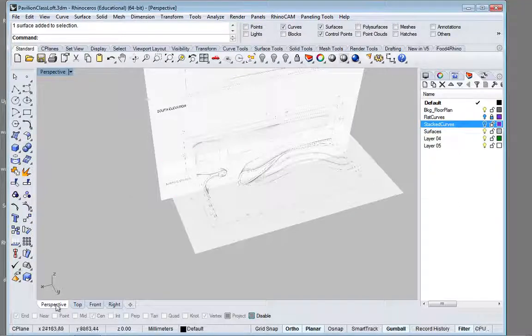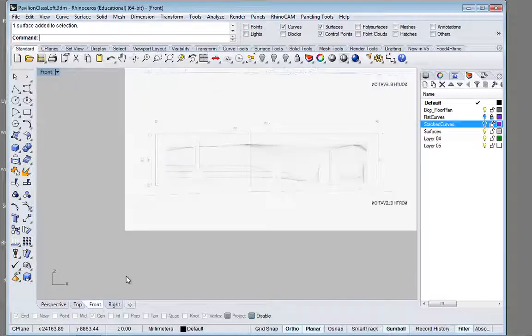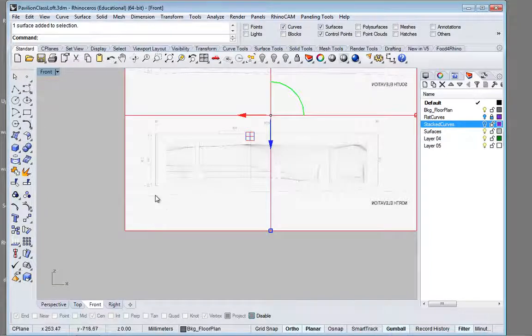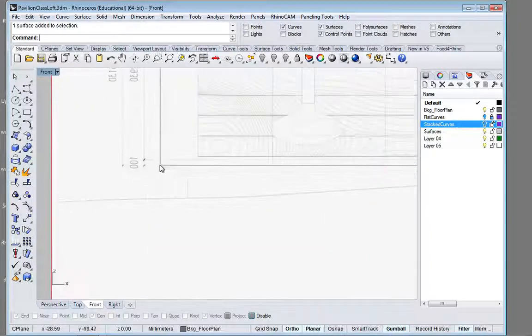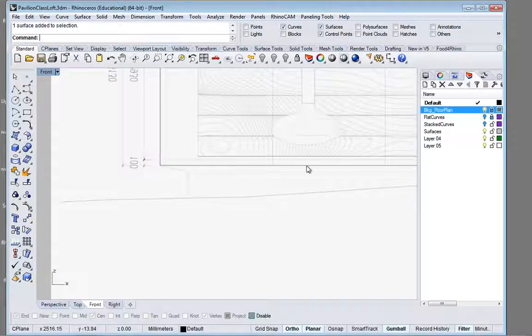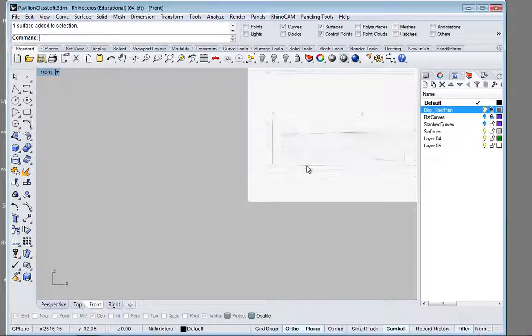So what I just did, so that you are following along, just select that front elevation, and I picked this corner point here, and I just typed move, selected this corner point, and typed in 0 so that it moved to 0, so that that base point that I'm going from is the same. Lock those layers down so that they're not going to be selected anymore.